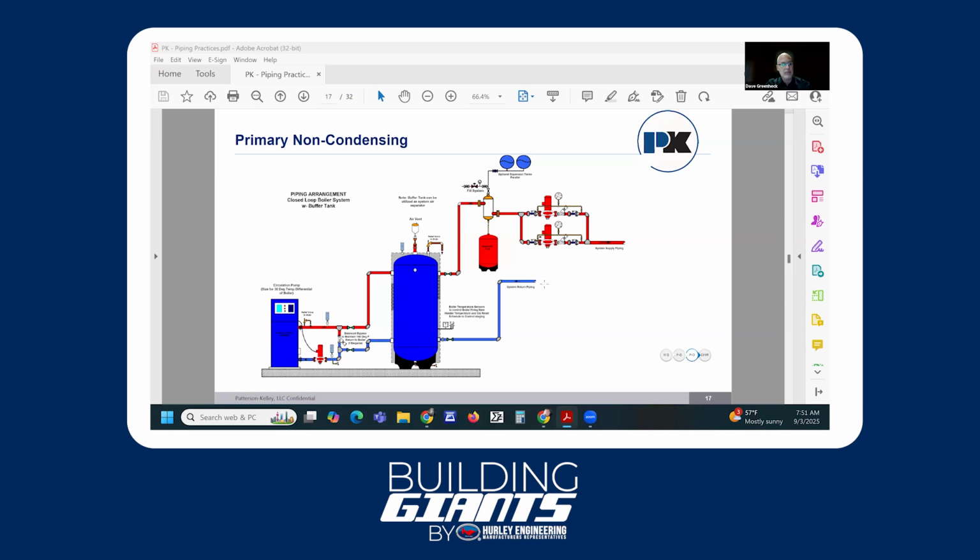And we just want to be exposed to more and more types of systems that we can see. That way we're comfortable with knowing what we see when we go into mechanical rooms and boiler rooms, right? This also tells the difference of primary versus primary-secondary, because they have pumps on either side, right? So you have the load pumps, but you also have the primary source pumps. Correct, absolutely. Source pump in this case.